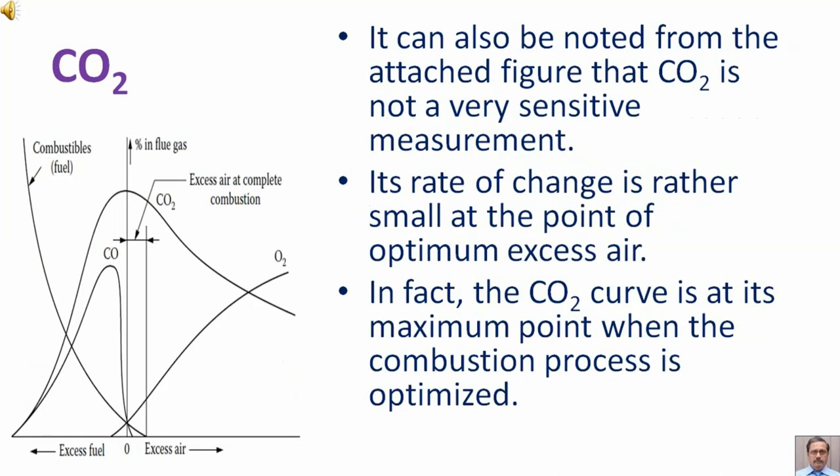It can also be noted from the attached figure that carbon dioxide is not a very sensitive measurement. Its rate of change is rather small at the point of optimum excess air. In fact, the carbon dioxide curve is at its maximum point when the combustion process is optimized.